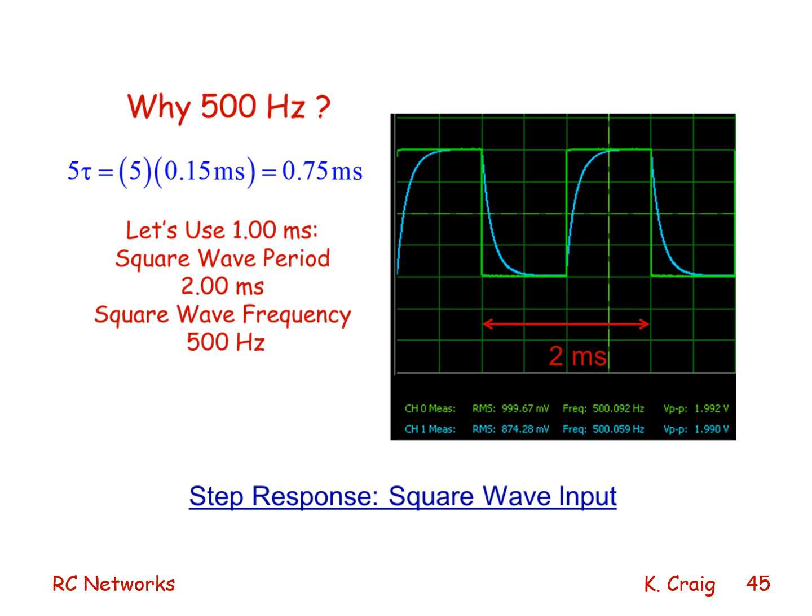You might as well wear a sign saying, I don't know what I'm doing. So you want to be able to predict what you will measure and then set the dials of the measuring instrument, in this case the oscilloscope, so that when you actually hook up your system to the measuring instrument, what you expect to appear appears.